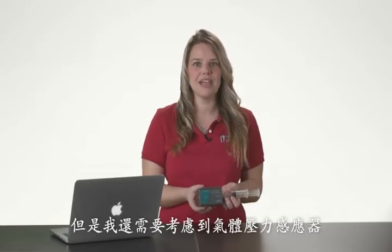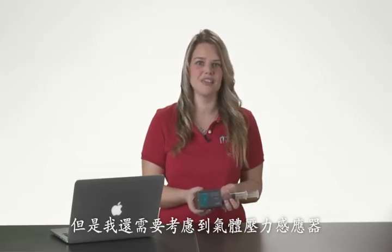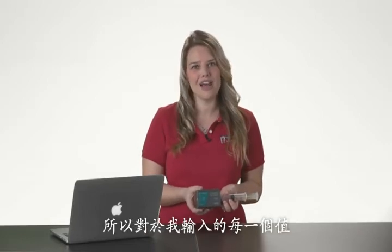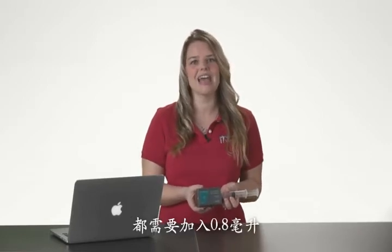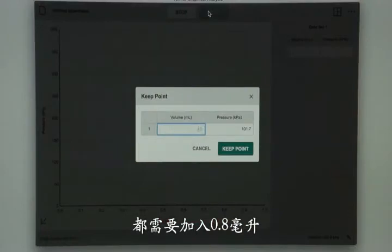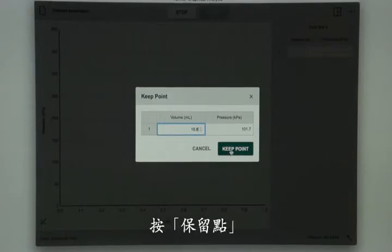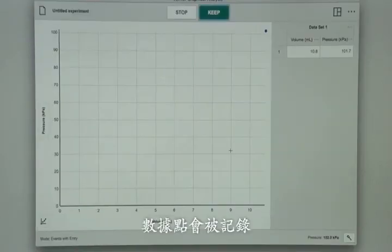However, there is 0.8 milliliters of volume inside the pressure sensor that I also need to account for. So for every value I type in, I will need to add 0.8 milliliters to it. So this volume is 10.8 milliliters. Press Keep Point. And now that data point is recorded.